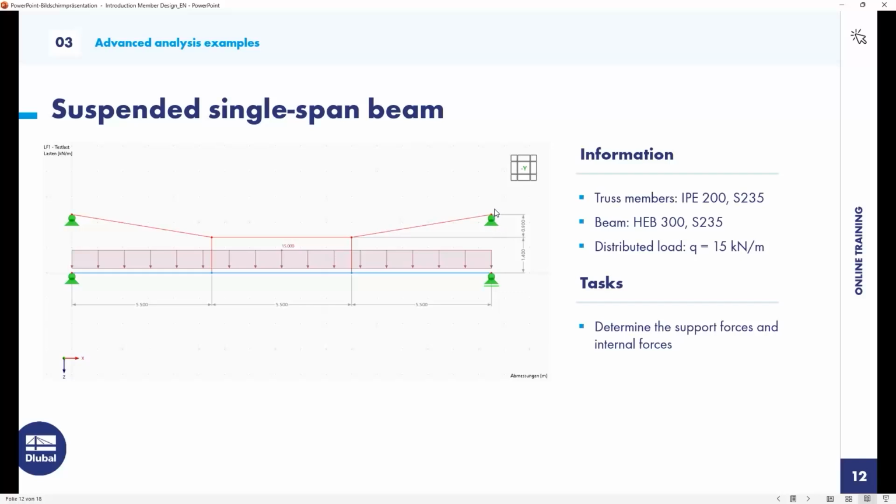That is also necessary because if you imagine that this is like a rope, then you will get tension on this member. And if we would make the deformation in X axis free, then this rope would simply go to the middle of the structure, and the function of this support would not be there anymore.